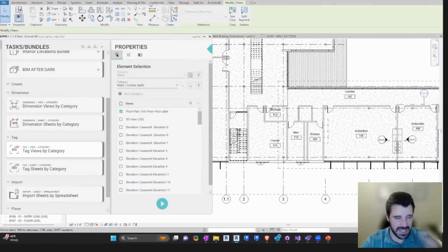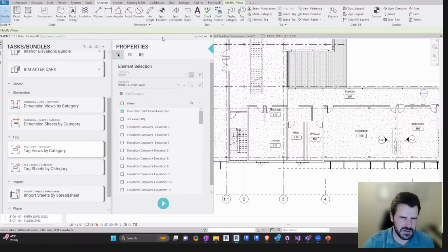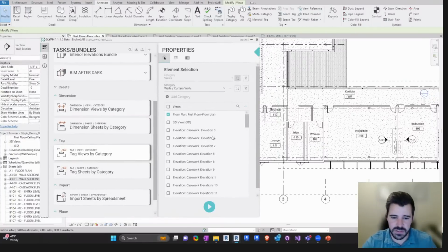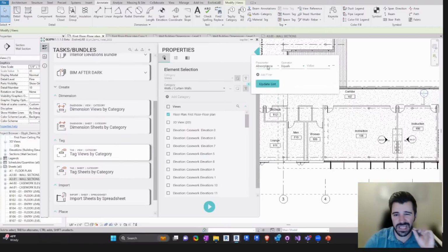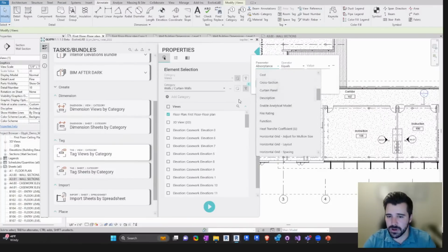And just on a side note, we know there is the toggle function in Revit, as you mentioned before, and Glyph goes beyond that essentially, because you can tag multiple views at the same time, and then you can use this button right here to filter out specific elements, in this case walls, that you want to tag, based on whatever parameter you want. So instead of tagging all walls, you can tag all wall type 2L or whatever it is, and so you're filtering the condition down. And then obviously the multiple views on a sheet thing, we could see.